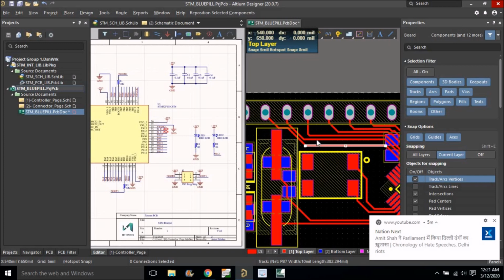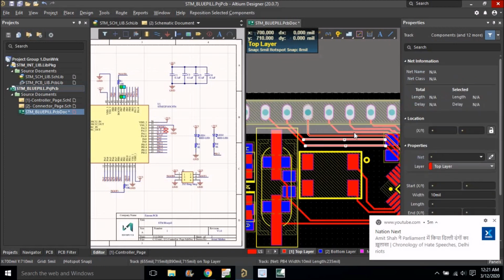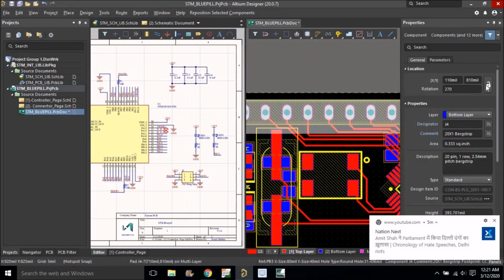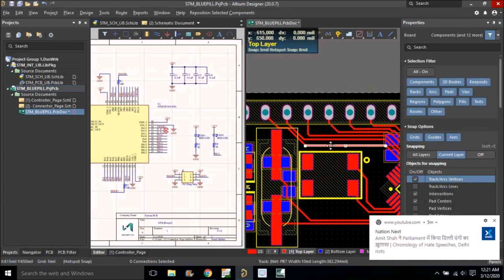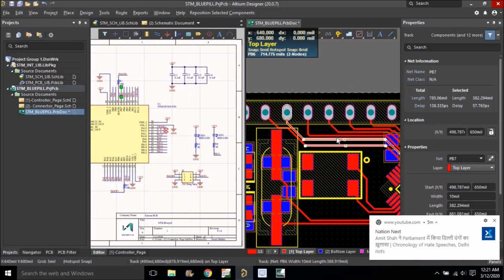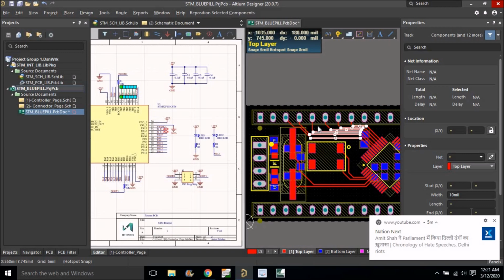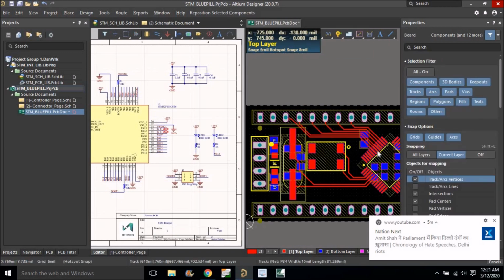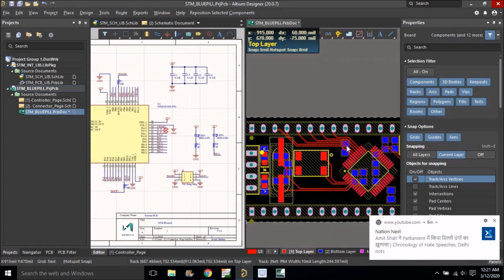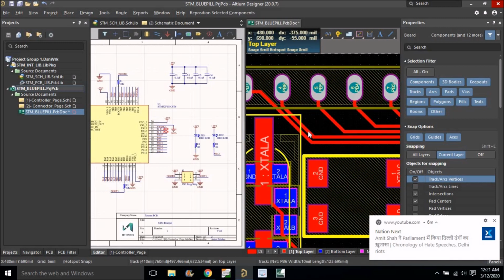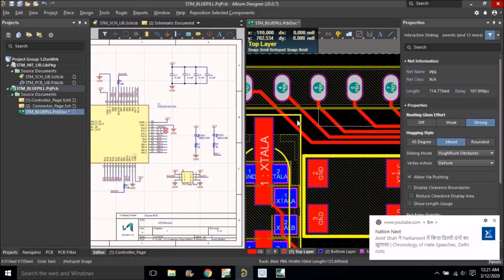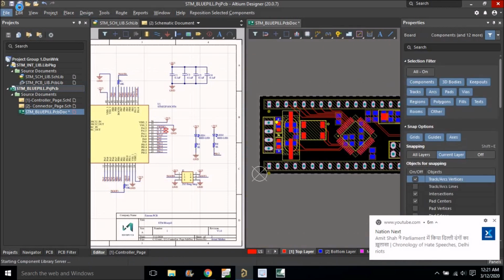So what I'll do, I'll just select these connections, hold on, so just lock this connector, otherwise it will select again and again. So press shift and click on each connection first, this. Now press tab, control alt and G. So all these connections will be proper now. This is the shortcut I always prefer. Right, now save the file.